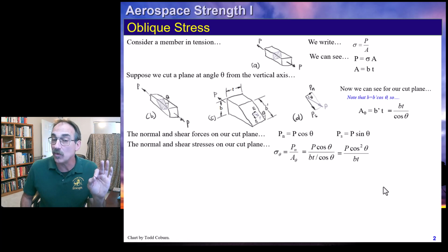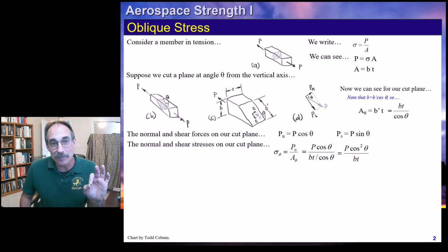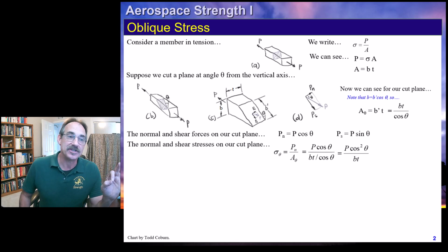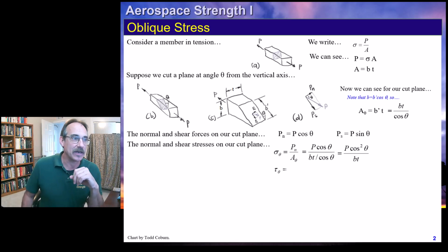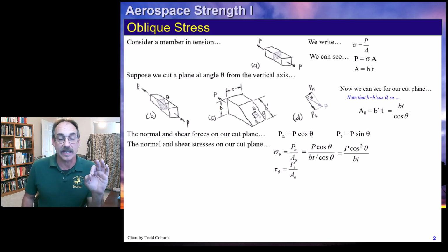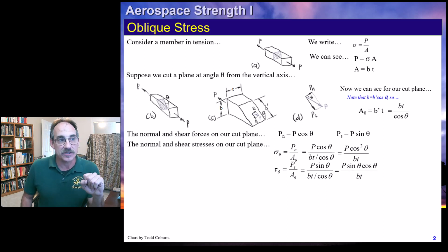Now this looks weird, and we start puckering up and getting all nervous when we see equations with a lot of trig, even though at some point most engineering students and industry professionals were good at trig. A lot of times once we go through higher learning, we start getting afraid of it and not doing as well. But this is completely doable by anybody that's passed an engineering undergraduate curriculum. Our shear stress, once again, is that shear force divided by that inclined area, which can be written this way. So we get these equations for the stresses.